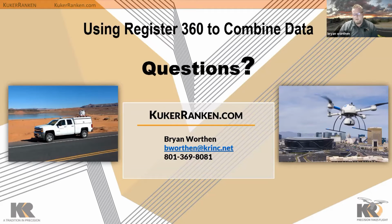But I think it's much more efficient. You can use fewer targets. If you run a project that's in RTK versus non-RTK, and then you compare them, there is a difference. So just start out with the best data you can on the photogrammetry side before you start comparing it with your terrestrial scan data.